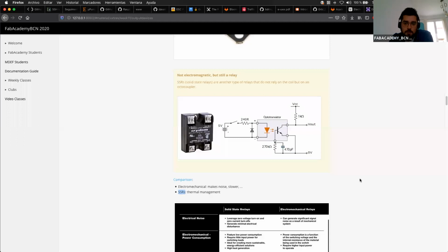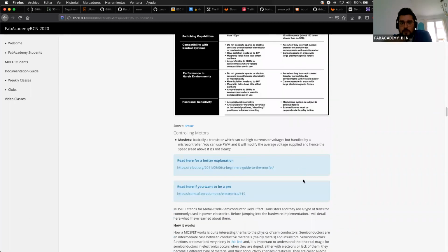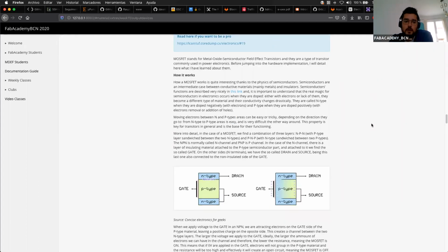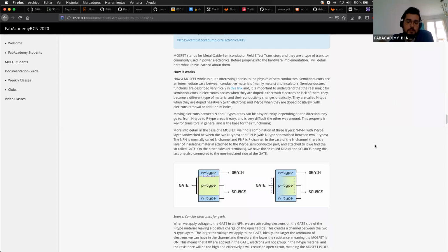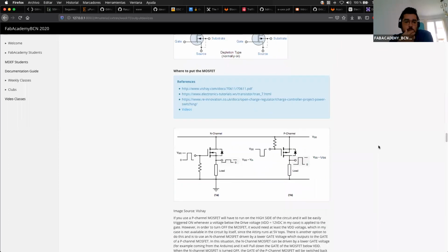So actually your power supply in that case is your USB. And the USB usually is 5 volts, 1 amp. So if you cut the cable and you connect the 5 volts to the Arduino, and you divide the cable in 2 and you connect another 5 volts, you will be rated to the maximum amperes and voltage that your power supply can handle. That is 5 volts, 1 amp.